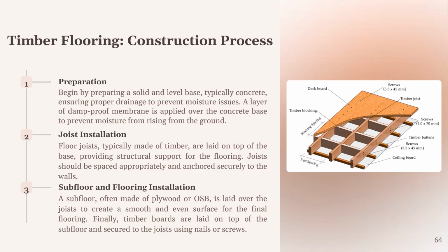The wooden blocks are fixed onto the concrete slabs using longitudinal nailing strips embedded in the concrete at suitable intervals. Sometimes we use a special type of concrete called nailing concrete as an alternative to the nailing strips, ensuring that the flooring nails hold the boards securely in place.